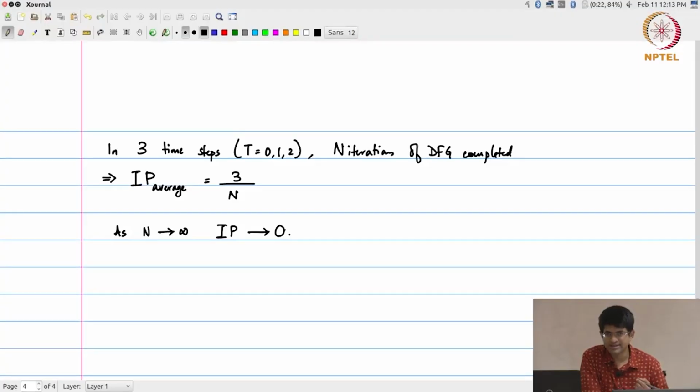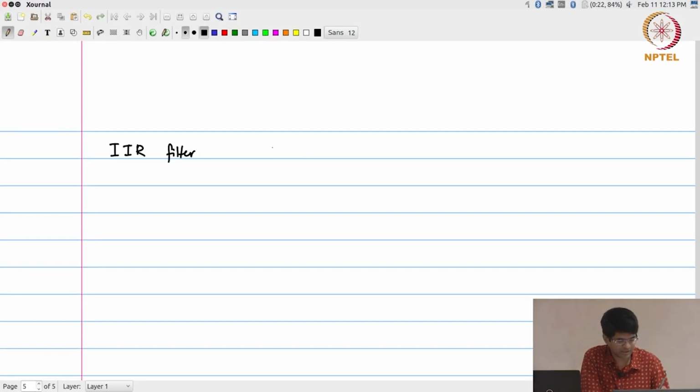To contrast this, let's go to the case of the IIR filter. Over here the data flow graph looked like this, right. So what is happening over here, the output of A is the Y, the filtered output. One delayed version of it is what goes as input to the M, which is basically multiplying by the coefficient small a, and that value is being fed back into the adder, which is also in turn adding whatever it gets from the source, which is x of n.